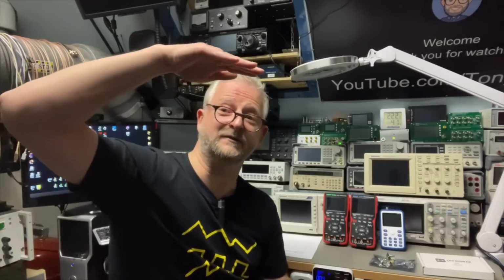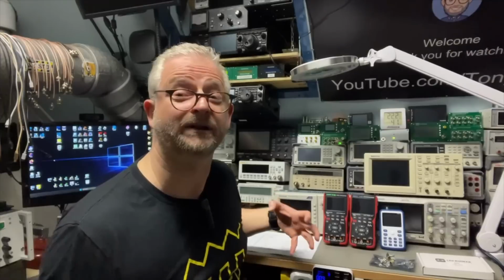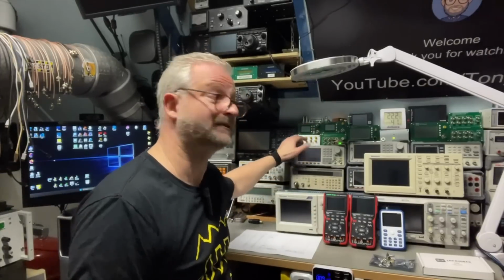I will be using the pulsar to verify the bandwidth of an oscilloscope. Of course, there are many ways to do this, but there are also many limits on the bandwidth of an oscilloscope. First, you have the analog circuitry, maybe we call that the analog bandwidth. At some point, when the frequency goes high enough, the analog circuitry or the op-amps just don't amplify as well, and then it will go down. But that you can easily check with the signal generator.